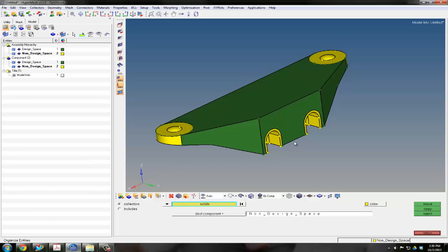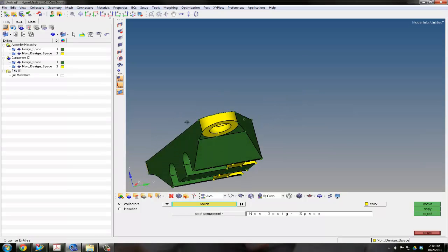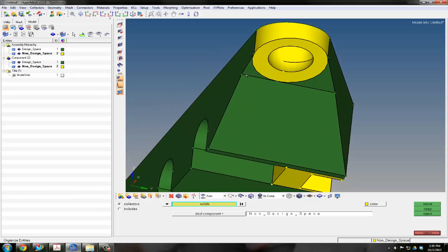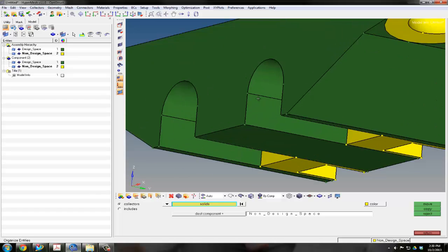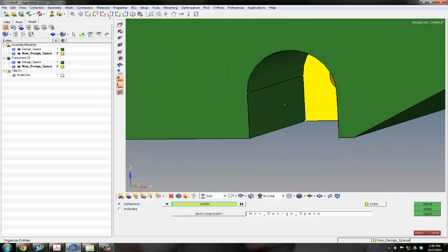The next thing we're going to do is prepare this geometry for meshing. So we could mesh it now, but it's going to have a few problems. Let me point out the main one we're going to have. Every time you have an edge like this, it's going to snap nodes along the edge. Or in other words, it's going to make sure that nodes are placed along this edge. This face, it's going to place nodes along the face, but it doesn't really care where on the face it is unless there is an edge. So on corners, that's obvious. It's going to put nodes along this corner, along this edge. But for example, this one, it will make sure that it puts nodes along this line as it passes through.